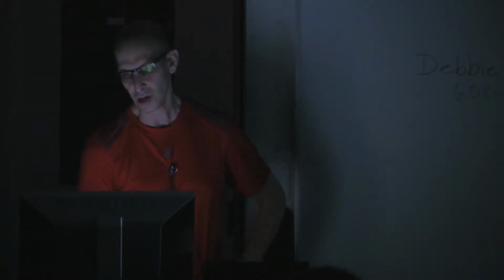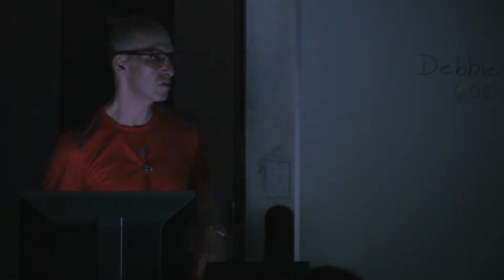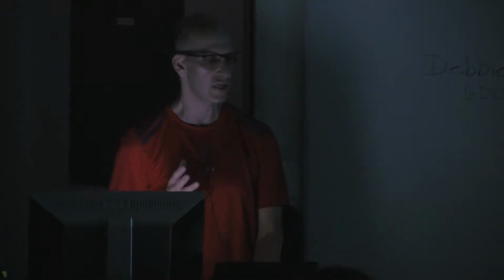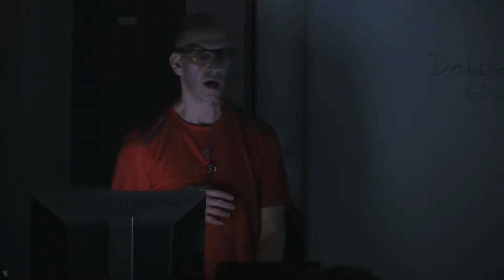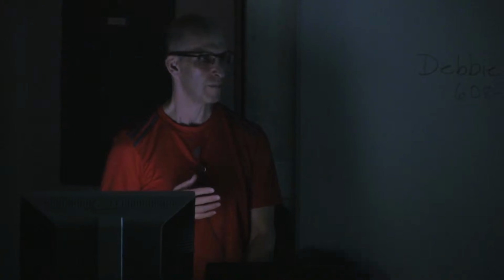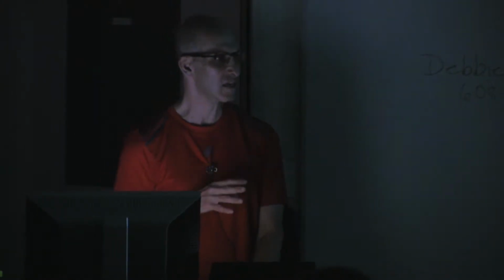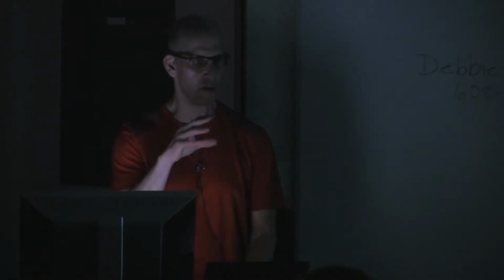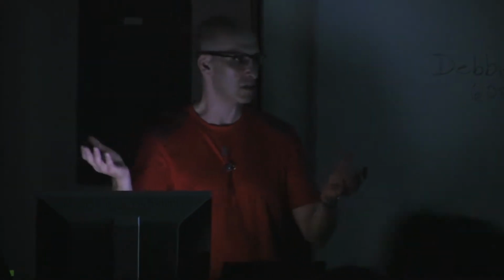Now, when we did this, one of the things we found was that we had to troubleshoot on the way. I call it troubleshooting, but I think this was sort of the evaluation. We wanted to make sure this would hold pressure, because it's very important to commission your machinery or your apparatus before you actually use it. And for us, if these leak, you can get an explosive hazard. Because if you get oxygen in with methane, what happens? Well, you now have a combustible mixture.